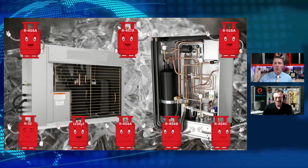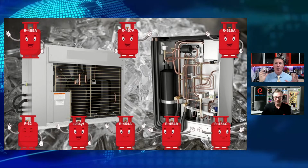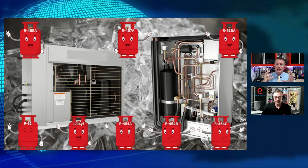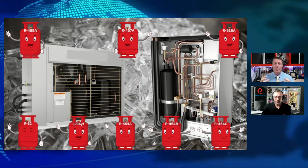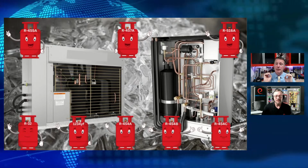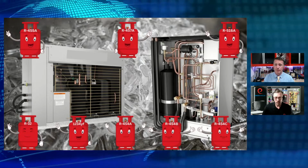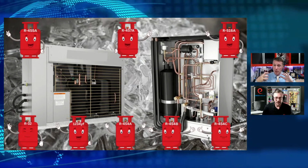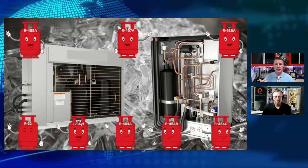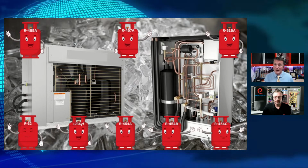So we've got 1234yf as well. 1234yf is our HFO refrigerant. Remember, our HFO refrigerants are synthetically modified HFCs. They still have hydrogen, fluorine, and carbon, but they now have a very unique double bond of the carbon atoms. So an HFO is an HFC with a double carbon bond. If you simplify it, it can break apart much easier if it is released. That's where the low global warming comes from. So very popular. Most of our vehicles are using 1234yf right now.